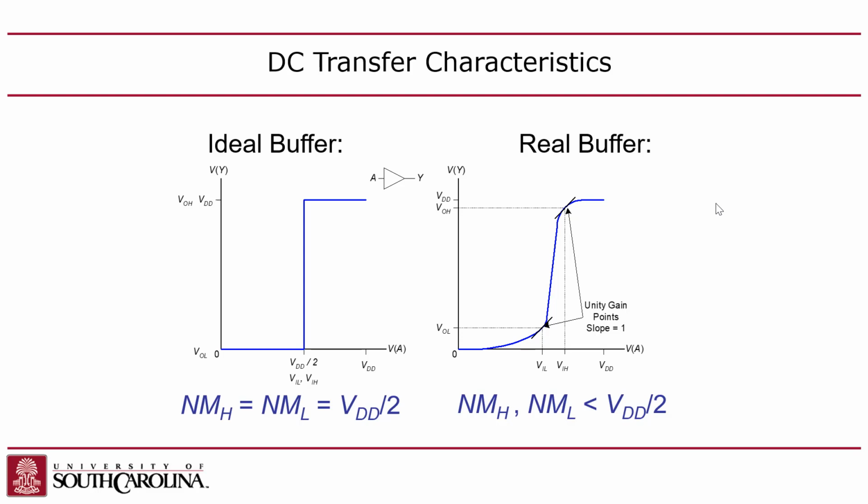So basically what that means is that the voltage input low, VIL, V sub IL, which defines the threshold for what is a logic low, logic 0, should be VDD minus 2, right? And VIH, which is the minimum voltage for a logic high, should be the same value, right? Does it make sense? So there's VIL, voltage input low, and VIH, voltage input high. Voltage input low is the voltage under which you have logic 0, and voltage input high is the voltage over which you have logic 1, right?